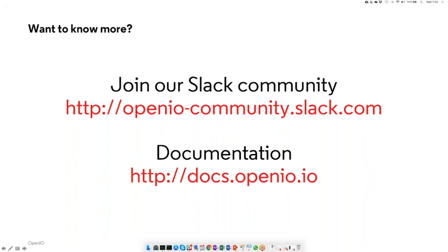Okay, the next one. One of the main issues with Raspberry is input-output performance via USB. Any other option to build a cluster? Yes. So we use the Raspberry Pi because it's the most common platform, and for one reason or another, many people already own them. But there are other options in the market. One of our engineers built a cluster out of Banana Pis, which is a more interesting platform because it also has a SATA port, so you can actually connect real hard disks to it, and the performance is much better because USB really sucks from the performance point of view. I don't know if Romain, you want to add something to this.